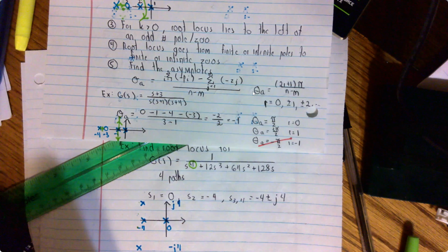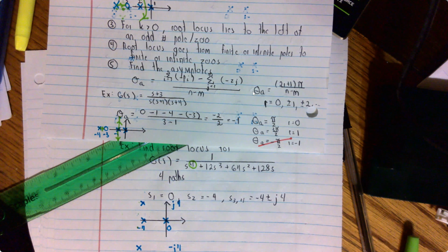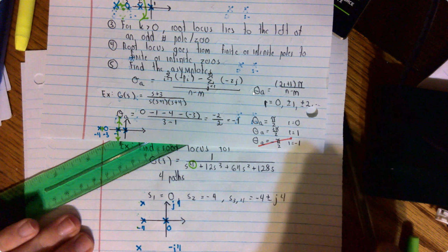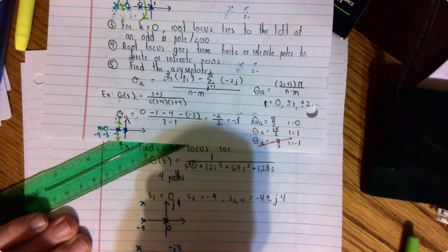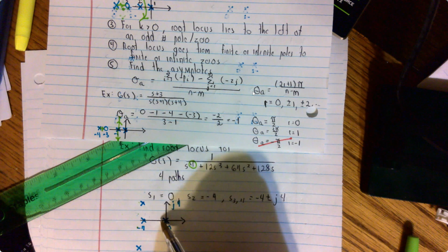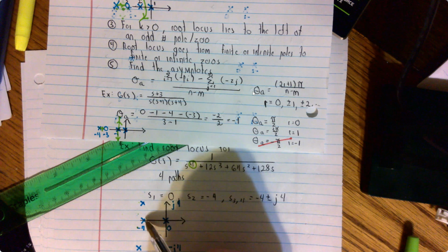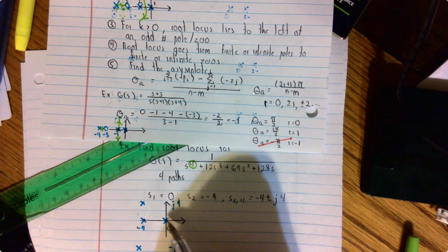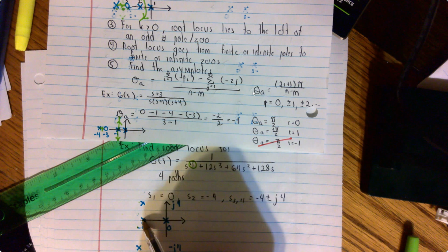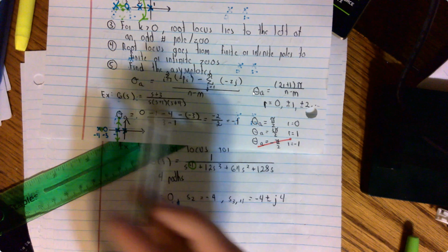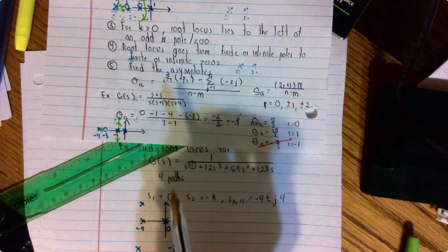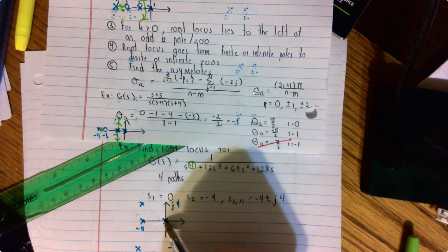Okay, so we know all that, and now what we have to do is basically find our sigma A here. From the pole-zero plot, we know the path is going to exist to the left. So there's going to be a path here because going from the right, here's the first one, here's the second one. And so there's a path that exists right here. So we know where it's going to exist, and it's going to go from the poles to zeros.